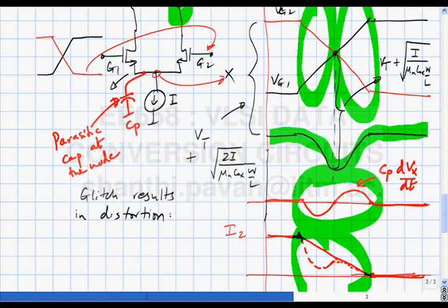There are several clever solutions proposed to clean this up. One solution is to deliberately cause a glitch every time, by some clever arranging logic, in such a way as to cause that node to glitch every time, regardless of whether there is a transition or not. That basically greatly reduces distortion. But the cleanest, safest way of doing it without too much effort is to make sure what?